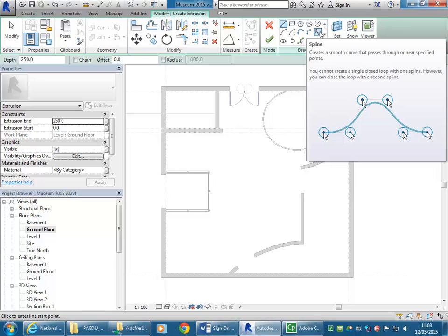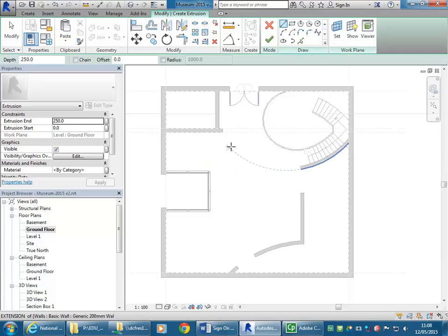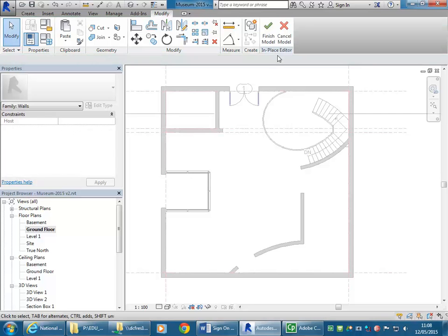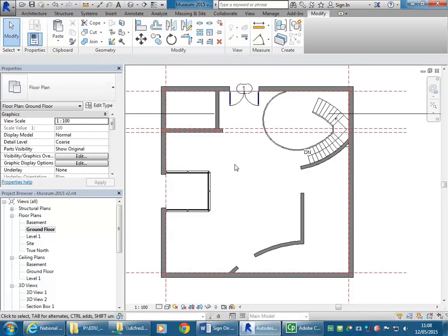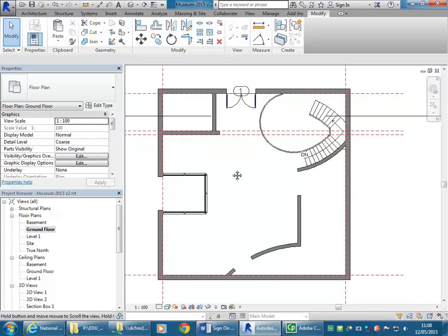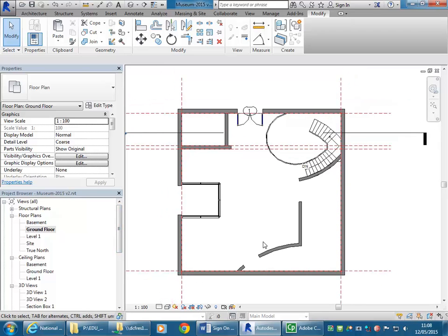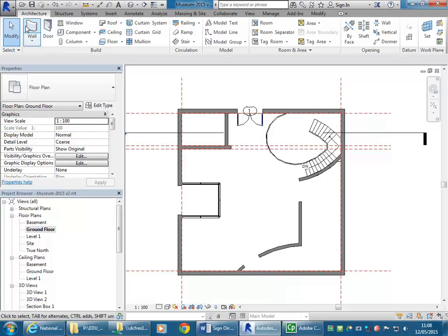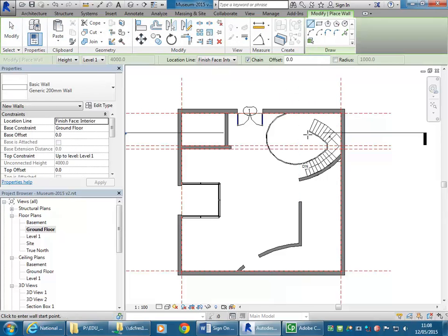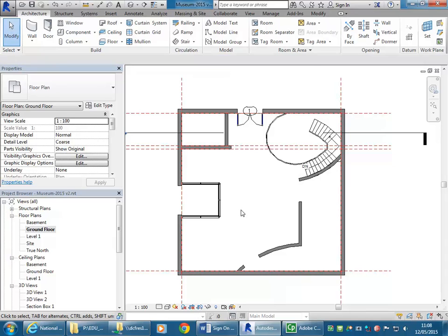So if you want to make more fluid curves, you can do that, but remember they're difficult to work with and difficult to build as well. Builders generally can't set those curves out easily, and you should be able to achieve most of the curves you want just using an arc. So again, try to get your main walls in before you go too far with the ceilings, but you'll need to put the ceilings in before you can put lights in.